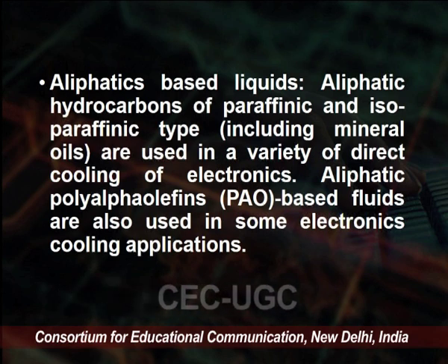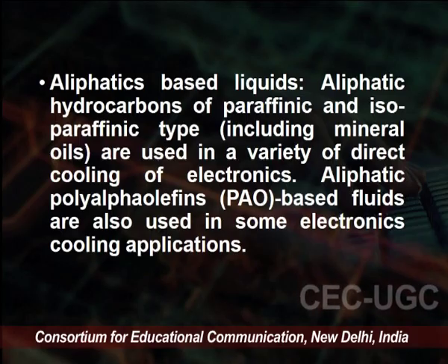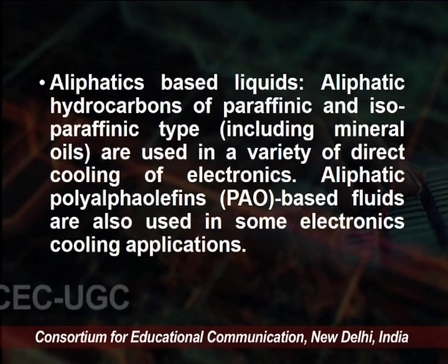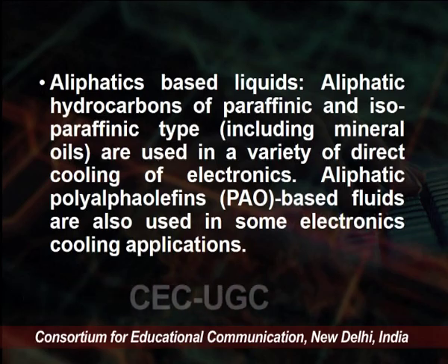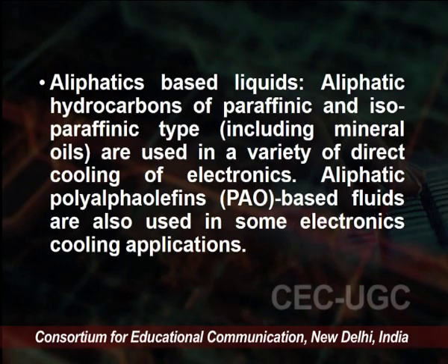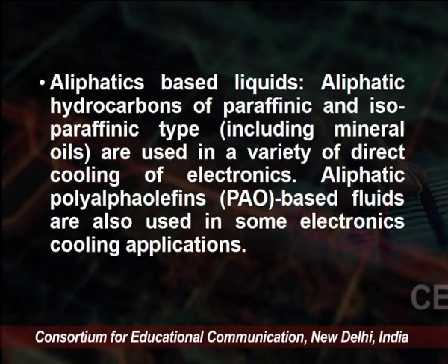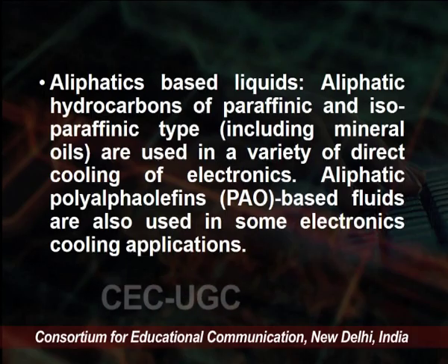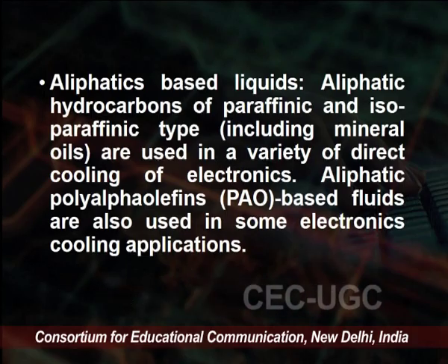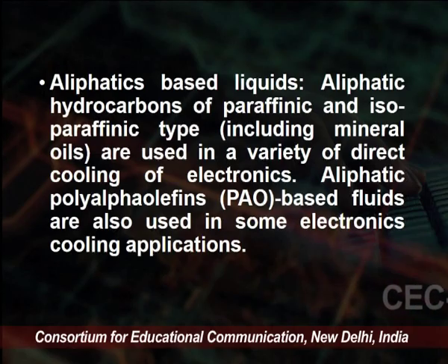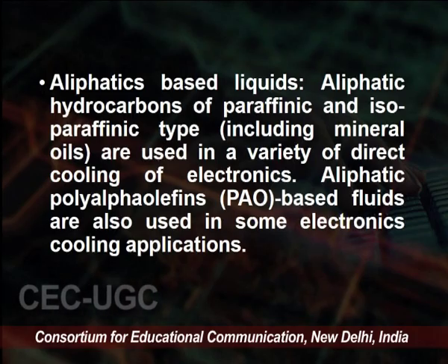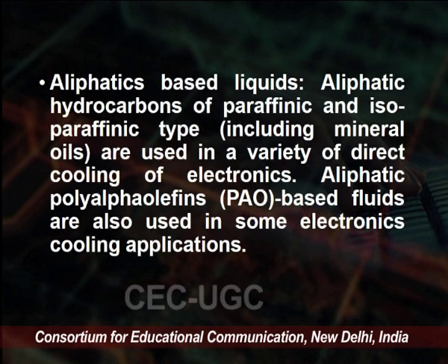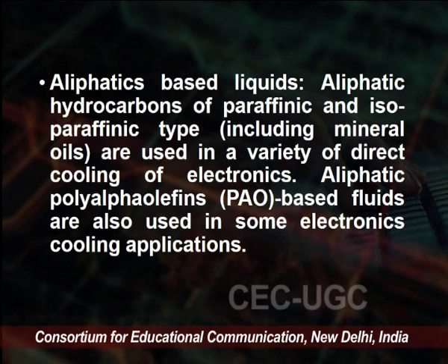Then aliphatic based liquids, in which we have aliphatic hydrocarbons of the paraffinic and isoparaffinic type, which include mineral oil and which are used for a variety of dielectric applications for the direct cooling of electronic devices. So it is just in contact with the system. Aliphatic polyalphaolefin, that is PAO based fluids, are used in some electronic cooling applications.